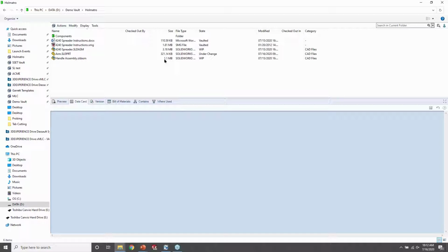those column types can actually be assigned to PDM users or groups. So you could maybe say for the manufacturing group that they're going to have a column for revision, and you can display it there. And then you can maybe assign a different column set to another group within PDM. But basically, think about what information would be helpful when you're browsing through the vault, and you can add that information to these column sets to make that process a little bit more efficient, right? So it's great that we're recording data, but it's also important that we're putting the data in the right location so that it's visible where it's most effective.